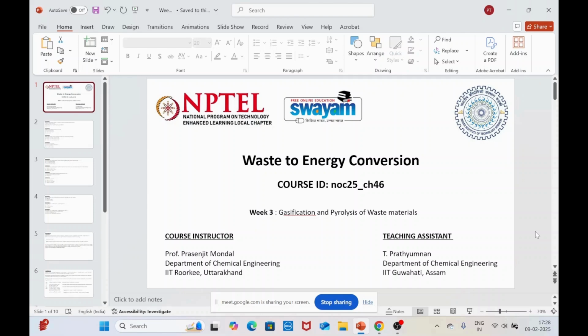Because of all these, the percentage of conversion, or the efficiency with which the material burns or gas gets combusted, will be more. Because of this, the syngas quality will be superior, producing a syngas with negligible tar percentage and less CH4 content.